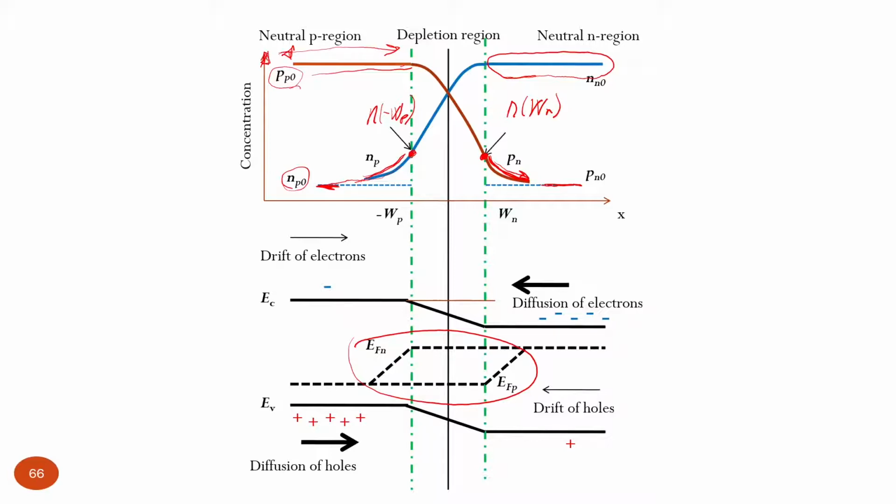So actually I want you to understand this, that in a p-n junction the key information which defines the current-voltage characteristic and current-voltage properties is the distribution of minority charge carriers in the p and n type regions upon injection of charge carriers at forward bias, and we will also consider in a bit more detail upon extraction of minority charge carriers from neutral regions when we apply reverse bias, because now we have only forward bias, so we inject charge carriers, we have higher concentration of minority charge carriers than thermal equilibrium.